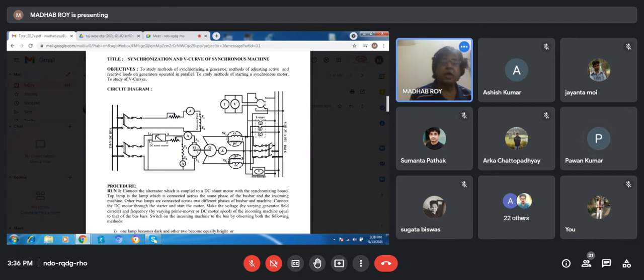Yes, sir. That shaft output is by the law of conservation of energy. If it is connected to the generator, so now if the active power is becoming zero, still it is a generator, because this motor is driving the generator. Yes, sir. But if it is a synchronous motor, then the power flow should be reversed. That means under any condition, this motor should not drive this generator. Got my point? Yes, sir.